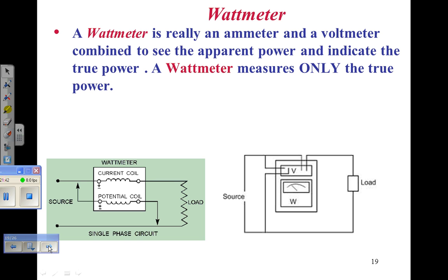Okay? Everybody see the difference? So they charge you the difference on what's going... No, they do not. They charge you for whatever you're taking in, apparent power. So if you have a very inefficient refrigerator, for instance, which is one of your biggest loads, other than an air conditioner, of course, if it's inefficient, so sorry for you. You're still paying the apparent power. You're paying for apparent power, right?